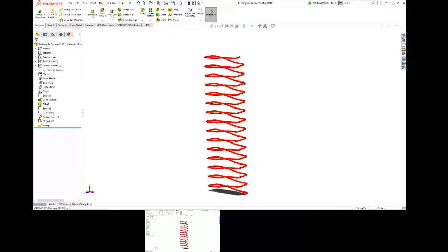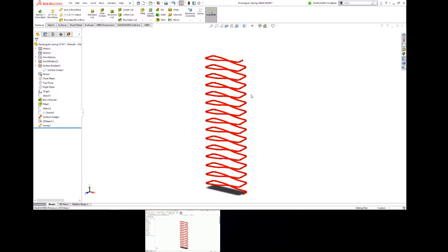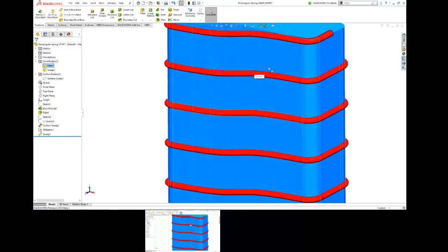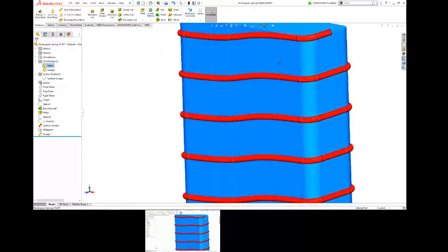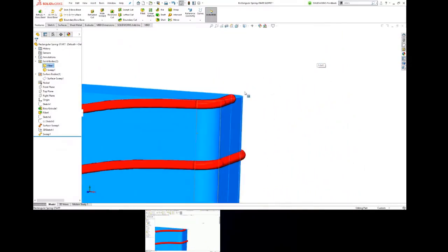Now that, if you put that on top of your bar, there's going to be interference. Correct. Can you move your guide point? Yes, I could, but not if I use that option for circular profile. That one always puts it at the center of your path. You have to draw the circular quadrant point on. Bingo. So once again, the question was if I wanted this to sweep on the outside boundary rather than on the center line, then I simply would have manually sketched the profile outside that pierce point.